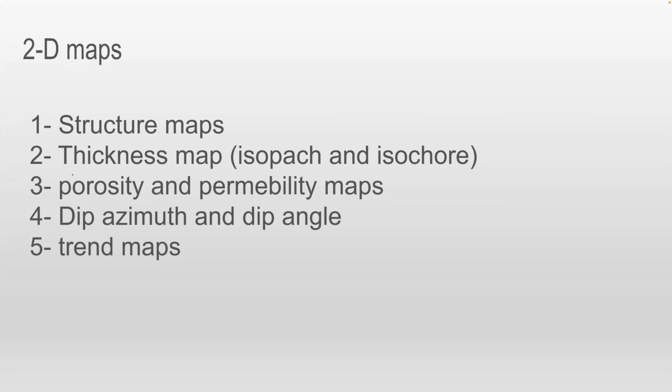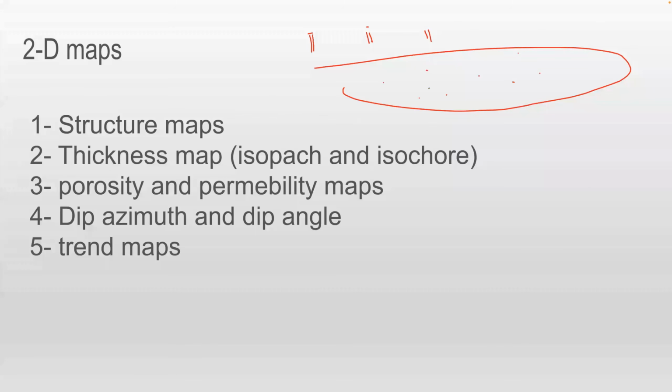So at first, you must import the wells. For example, you want to create a static model for an oil field with 100 wells. You must at first import the wells, wellheads, and also the tops of the formation. For example, you have a field with different wellheads. So you must import these wellheads at first, the survey of those wells, and the tops of those formations.